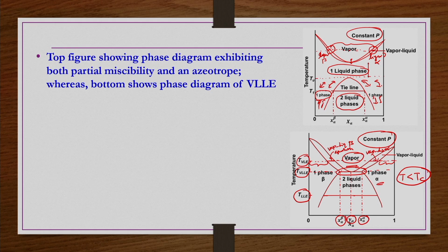So, this is the case where a minimum boiling azeotrope is there. So, then you can easily visualize the coexistence of these three phases, one vapor and two liquid phases, but not necessarily should all VLEs look like this. In the next lecture, we will be taking a problem and discussing how this PXY diagram looks, and there you will find that there is no azeotrope present at all. Okay. So, more complicated things than these are also possible, but for simplicity, for easy understanding, we have taken this case. Okay.